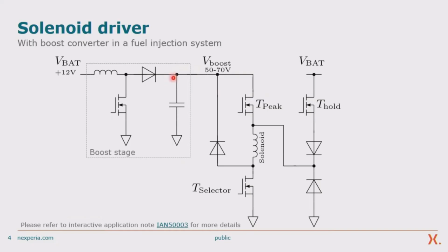All right. Thank you, Reza. I have one more question for you here. Which kind of diodes should be used in the boost stage of the solenoid driver? Yes, so here at the input, I would recommend to go with the 100-volt Trench Schottky, and depending on your application, it should be 10 to 20 amps here. And for the freewheeling, which I also didn't discuss, I would recommend to use a 100-volt planar Schottky in the range of maybe 4 to 5 amps.